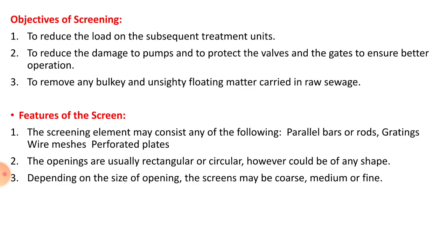Objectives of the screening: to reduce the load on the subsequent treatment units, to reduce the damage to the pump, and to protect the valves and the gates to ensure better operation. And the third is to remove any bulky and unsightly floating matter carried in the sewage, raw sewage.